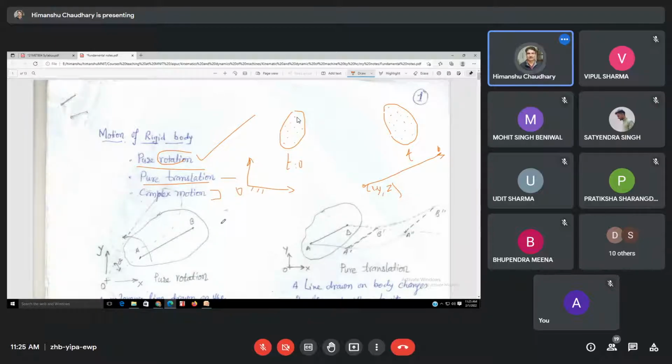So in position analysis for a rigid link, suppose I know the position of a point on this body, because the position of this body is known. So the position of this point is known. Any point. And then I draw a line on it. So there are two things: one is rotation, second one is translation. Here rotation and translation are both simultaneously happening. So I measure translation by locating a point, and I measure the angular displacement by drawing any line over it.